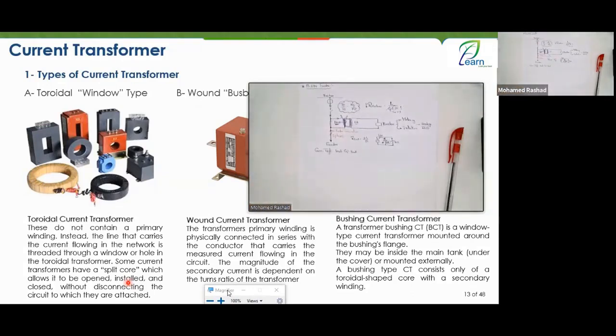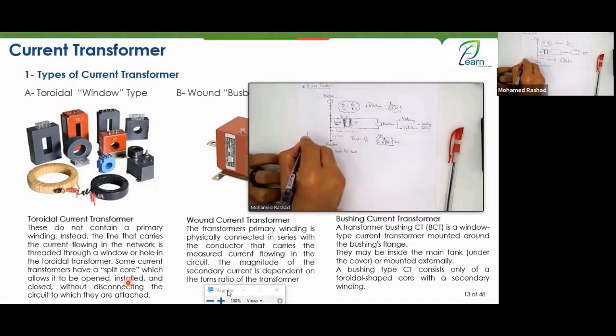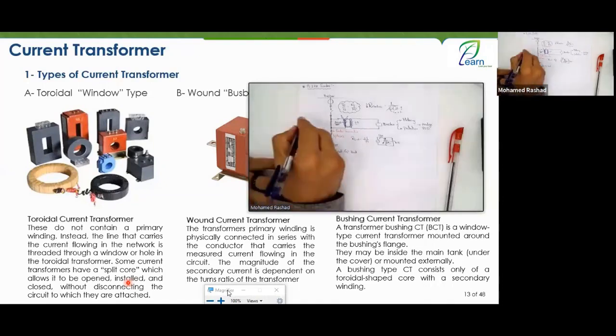That's number one. Okay, number two, there's something called a split core. What is called a split core? As an engineer, it comes here in your cables where you find this cable, for example, the red phase, the yellow phase, and the blue phase, and here they are connected to your cable in this way. This is the part of the switchgear terminals that are located here, and your cable is connected to them, which then goes to your load, or goes to the generator, or goes wherever. I have something called the split core. The split core CT is a CT that looks like this. Here it is.